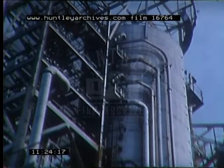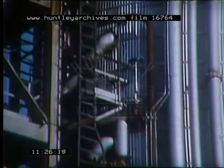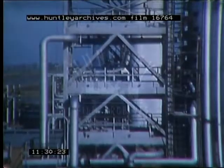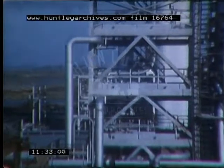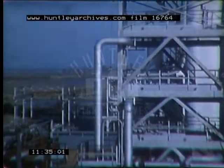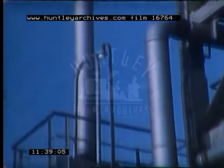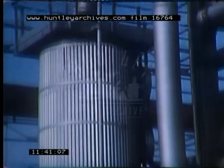At various levels down the tower, the composition of the descending liquid corresponds to that of a required product, so a side cut is taken off. All the side cuts are piped away from the tower and stripped in this tall stripper tower.